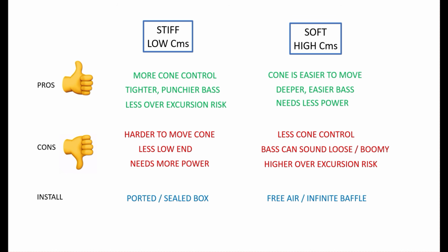And it's why the SPL guys love stiff suspension subwoofers, because you can throw more power at them. The sub will stay more controlled, more centered in the magnetic gap, so they'll take more power, right? More power means more loudness, and that's why they like them.